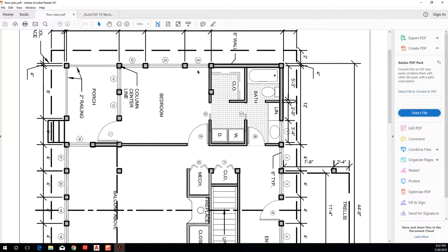So when you're drawing a floor plan or a set of drawings, right, the methodology behind creating a floor plan is you cut a building at a 3 to 4 foot range and you draw everything from the cut below, right, assigning it an appropriate pen weight, okay?